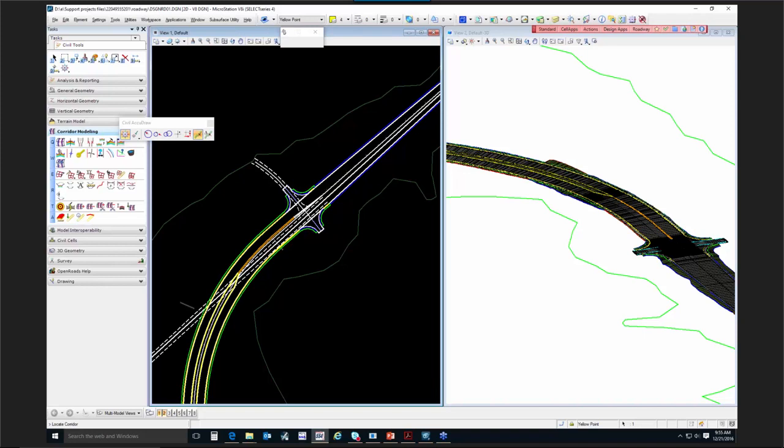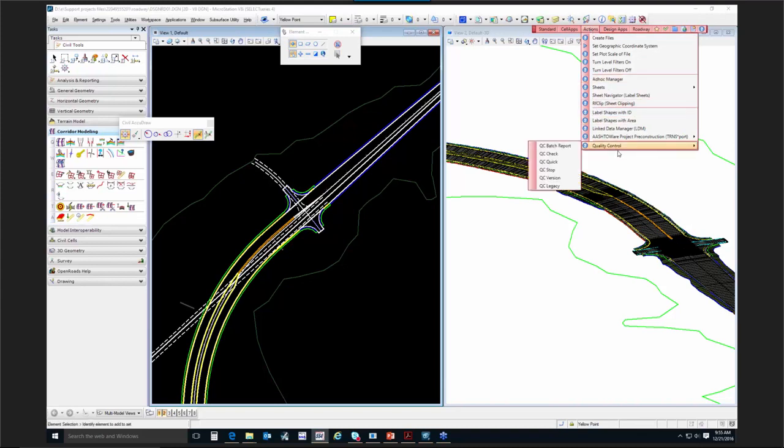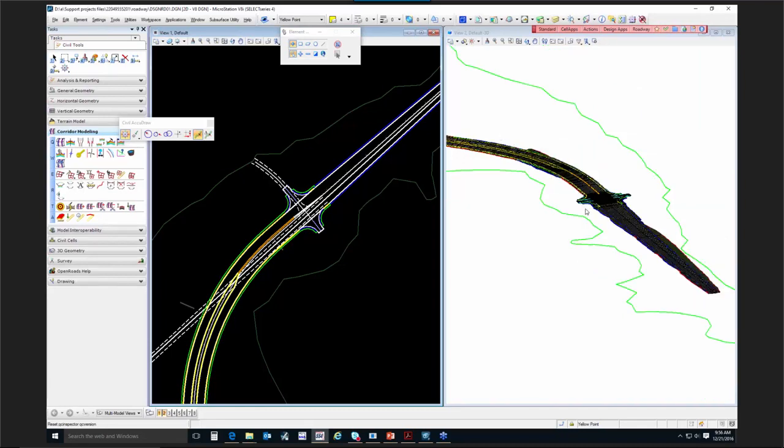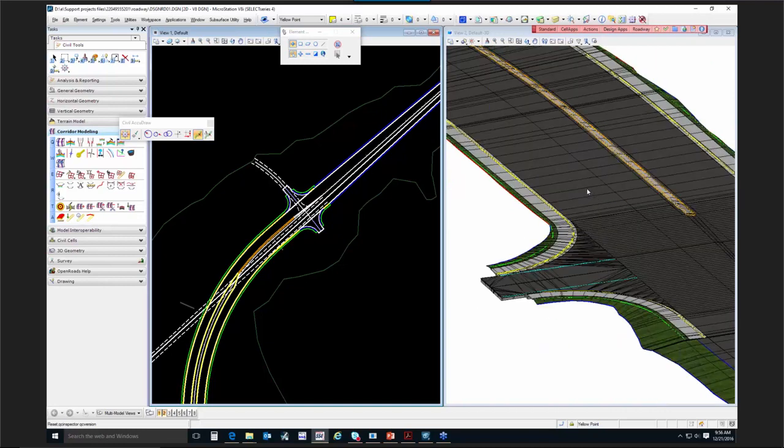Will the QC check in our CAD MicroStation software be enhanced to capture the 3D conflicts instead of just 2D elements? It already does. It's not really conflicts, but the QC check is checking to make sure that the levels that you've drawn the model data on is where we want you to draw them. As long as you're using the templates that we deliver, you're going to meet QC for your model.